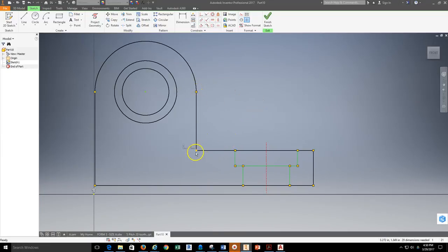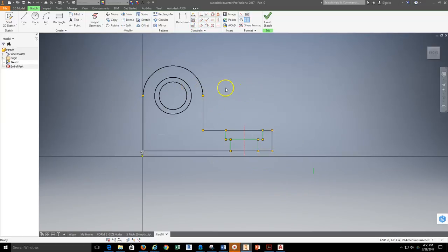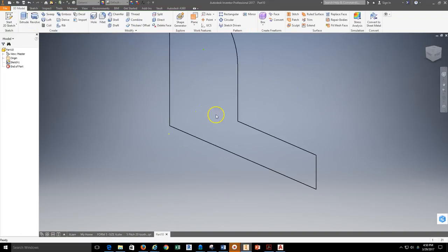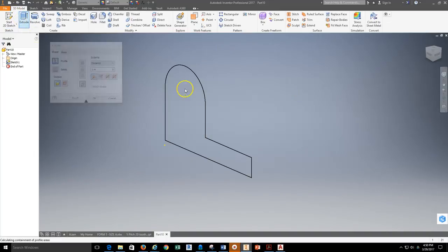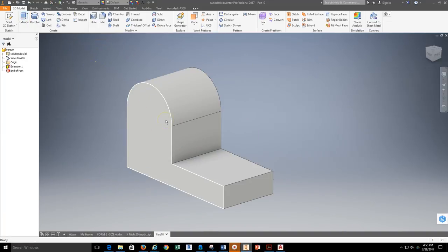Now, if I wanted to show all constraints to see if there are constraints, there are some constraints that have been placed, yet not high-level constraints such as tangents. So the only thing I'm going to be able to do at this point is extrude a closed loop. So I'm going to delete some of the geometry inside of this area, because this geometry could upset the actual extrusion process. I'm going to finish the sketch, grab my extrude tool, and I should be able to grab that entire closed loop profile, and then I'll extrude this 3 inches, because that's the depth to do the extrusion to.